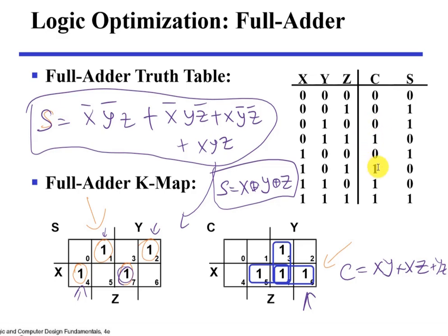Okay, let's start from this. 1 if x and then y both are 1. That's first case, right? The sum is 2. Or if the sum is 1 plus we have the carry in. Okay? So sum between x and y is 1 plus carry in, or we have x and y 1. So in that case, we have the c equal to 1, right?